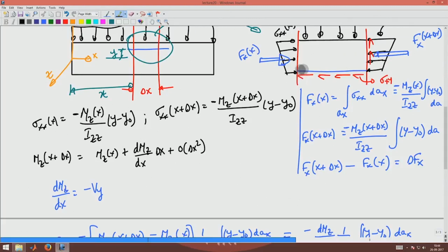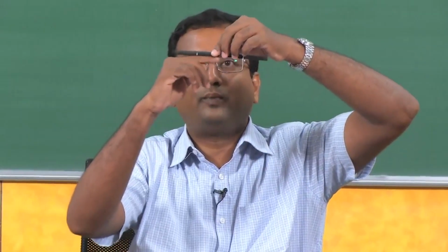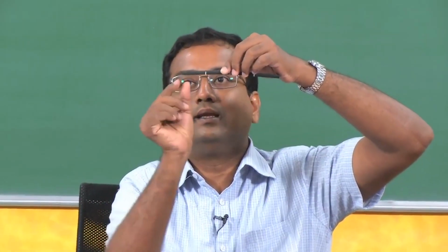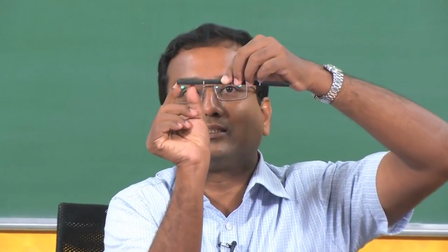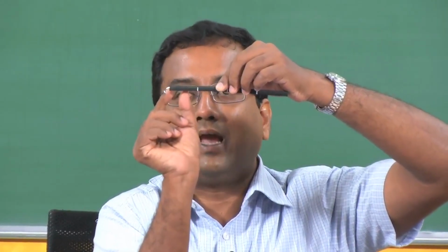This shear stress acts over an area whose length is delta x and whose width, into the plane, is b. If I have a cross section like this, the shear stress is acting on this plane, and hence its width would be this distance b times this distance delta x.